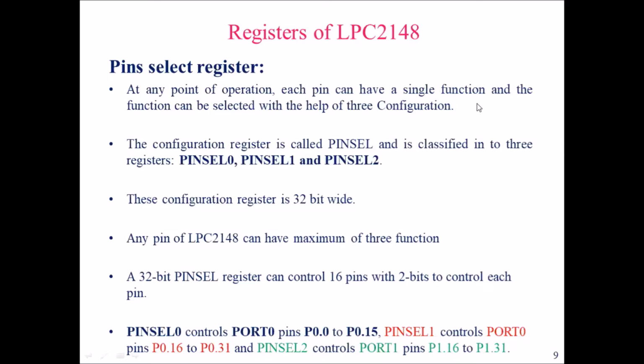At a time, if a single pin has more than one function, you can make use of only one function, and that should be selected by using this pin select register. Let's see how to select a single function from the pin. The configuration register is called the pin select, PINSEL. In short form, you should represent it as PINSEL, all in uppercase.